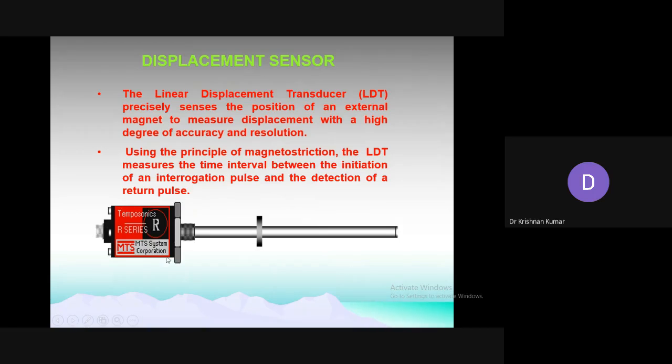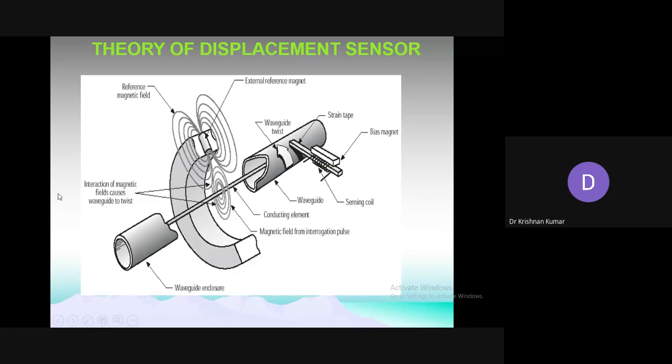The magnetic position will be here. This is the permanent magnet. Whenever this is connected, the magnet can move. So there are two parts, one is the fixed part, another is the moving part. When the magnet is moving on this, induction is created. Then the voltage changes will be there. That voltage change we can calibrate to the distance. So that will give you how much it is expanding, how much it is contracting. So this is the method.